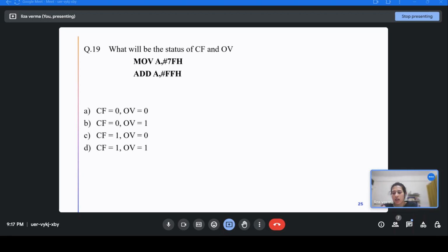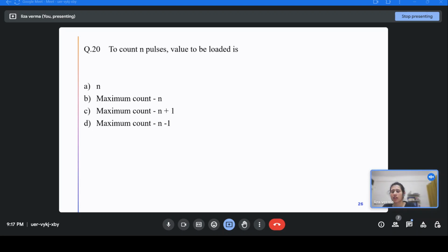In this case, the carry flag is set in both cases. If it's unsigned, it's explicitly mentioned. Whether we should ignore the flag or not matters. But the carry flag gets set here, and the overflow is 0. Okay, I think I've answered it.